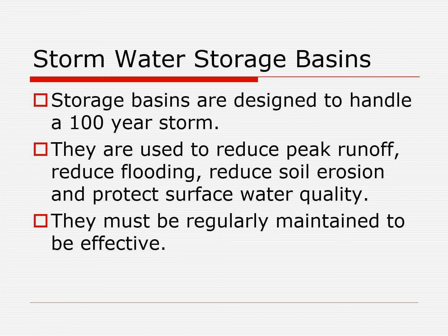Now, how much rain falls for a 100-year storm also depends on where you are. So if we go back to the rational formula, I had that Q was equal to C times I times A. Well, I was my rainfall intensity, and that will be given in a unit of rainfall per period of time, right? So like inches per hour is one that we may see. So you guys know in this area, a 100-year storm is a rainfall event of approximately 8 inches of rain in 24 hours. That is a pretty significant amount of rain.